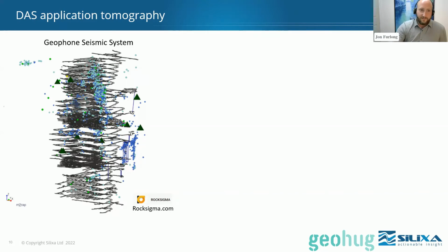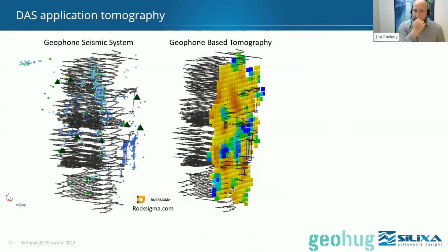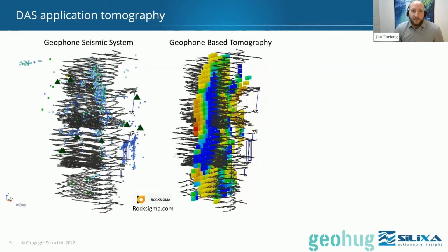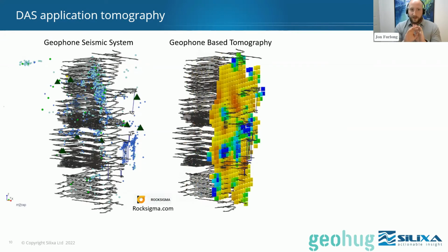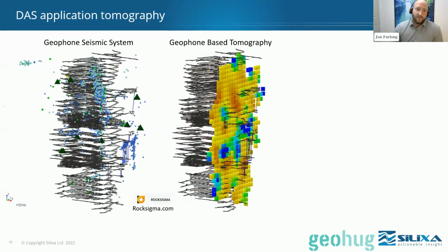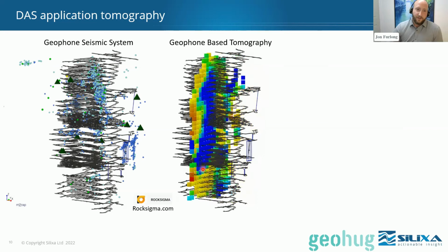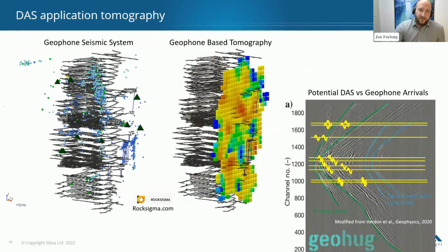So using those microseismic events and the geophones, they were able to invert for their tomography. This is their P wave velocity model through the mine. So it's kind of doing an MRI of the mine itself. And you can see where those values turn to deep blue, that's where the P wave drops to 0, which correlates to where that rock mass has been excavated. And then those cells change their P wave velocity and bend around the excavated ore body.